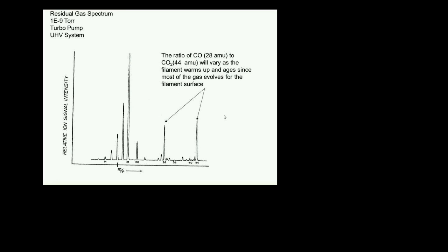It might have been exposed to neon at some point, or maybe it was exposed to air for a long time, right? Now neon is outgassing from the pump itself, and in this particular case, with an ion pump, you're going to have to add 20 and 22 to your list of usual suspects. They're always going to be there in your background spectrum. So they become part of your everyday operation.